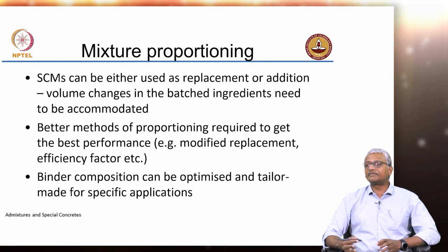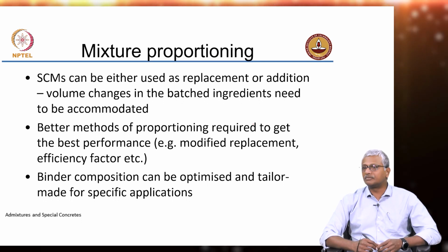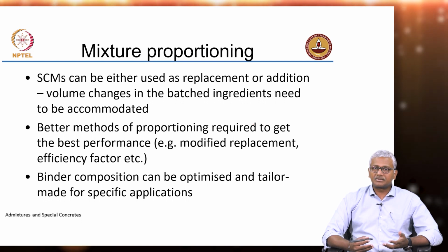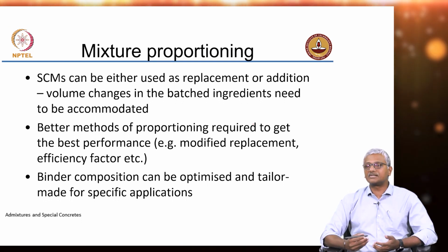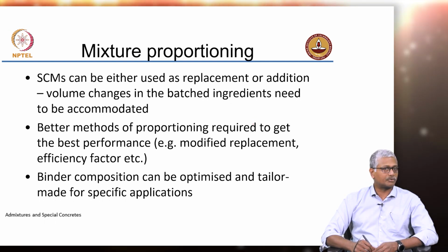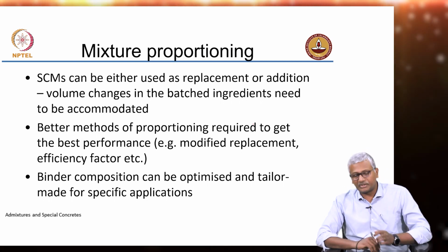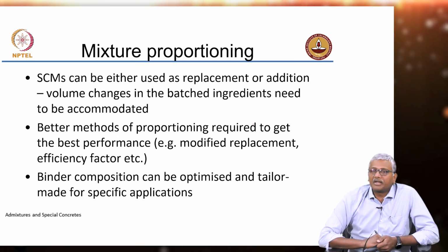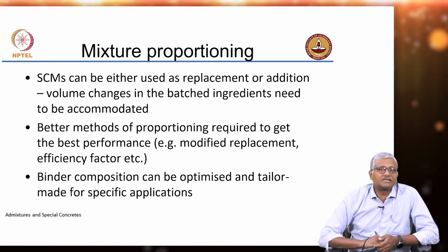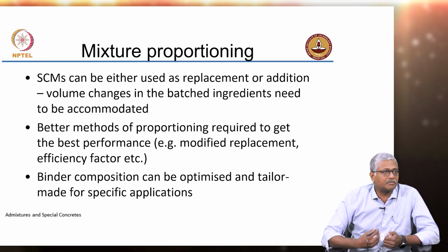Of course, apart from this, the availability will be a big factor which will define which additive you get to use, right. Something needs to be transported over a long distance, it is going to add to your cost. So, it is not really something ideal that you want to use in your system. Now, when you make concrete with the mineral admixtures, replacing your cement, you can consider various different ways of accommodating the volume brought in by the mineral admixtures.